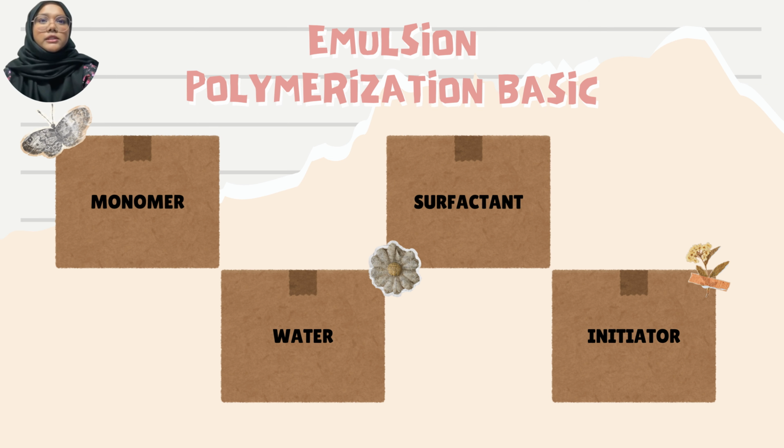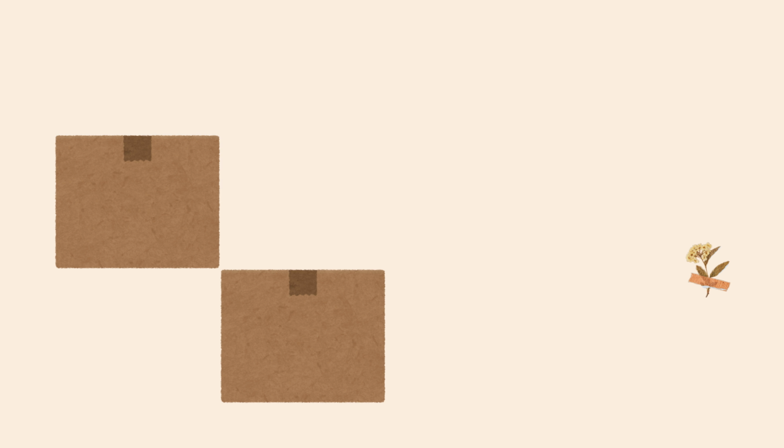So here are the emulsion polymerization methods. Emulsion polymerization is a process that uses an aqueous medium to polymerize monomers. The components include the monomer, in this case ethylene gas, not a typical candidate for emulsion due to its low solubility in water. Other than that, water acts as the continuous phase, and surfactants stabilize monomer droplets and growing polymer particles. Lastly, an initiator, often water soluble, like persulfates, to create radicals in the aqueous phase.